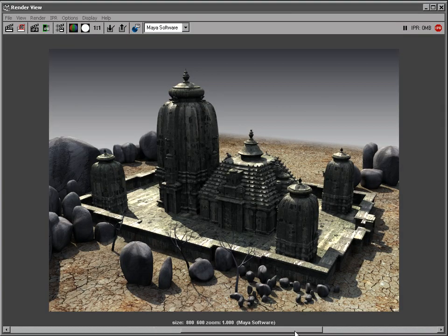And if we go back to the other, I've raised my intensity a little bit so we can see the shadow characteristics a little better here, but this is a much superior way of creating the fill than the directional cluster. A little more expensive. There's more lights, more shadow maps to calculate, but not too bad a hit.